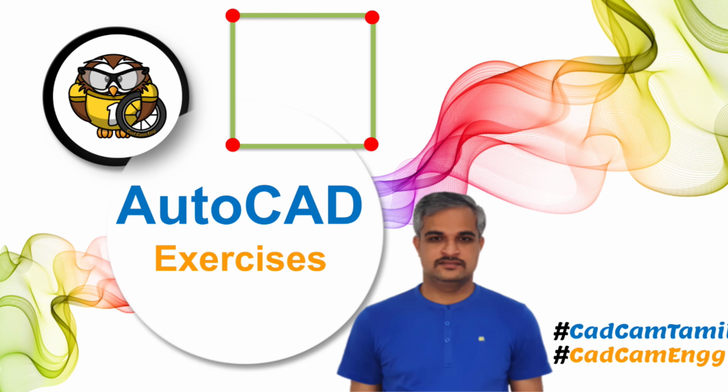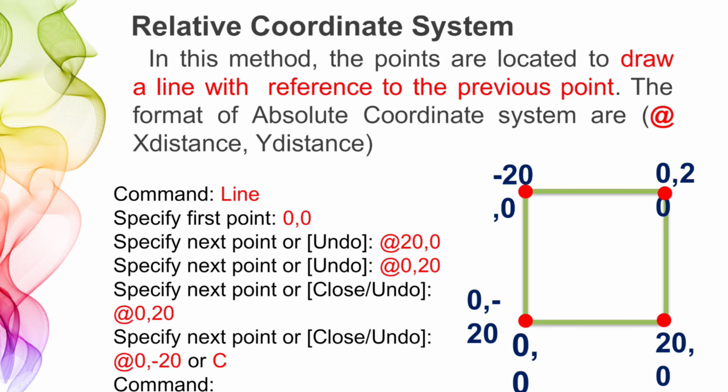Welcome back, dear friends. In this video, we are going to learn about the relative coordinate system, and also using AutoCAD, we will find how to draw this rectangle using the relative coordinate system. First, what is the relative coordinate system? In this method, the points are located to draw a line with reference to the previous point. So this is a very important one.